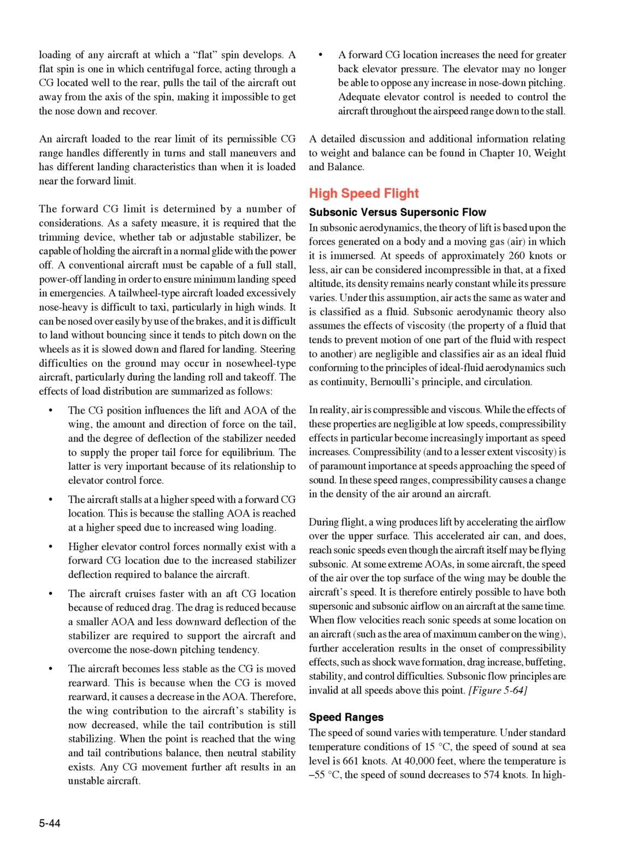High-speed flight, subsonic versus supersonic flow, and subsonic aerodynamics. The theory of lift is based upon the forces generated on a body in a moving gas, air, in which it is immersed. At speeds of approximately 260 knots or less, air can be considered incompressible in that, at a fixed altitude, its density remains nearly constant while its pressure varies. Under this assumption, air acts the same as water and is classified as a fluid.